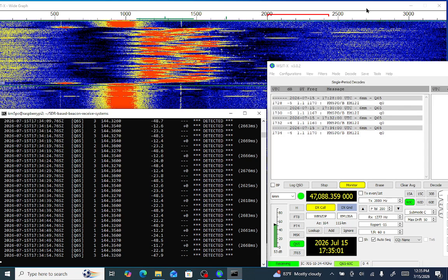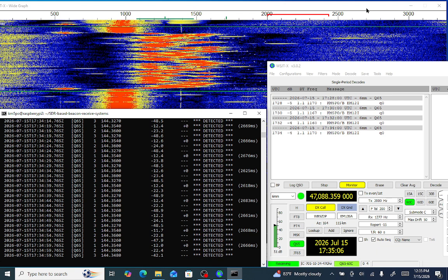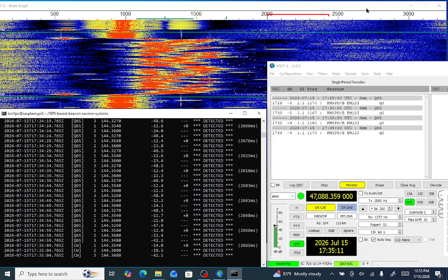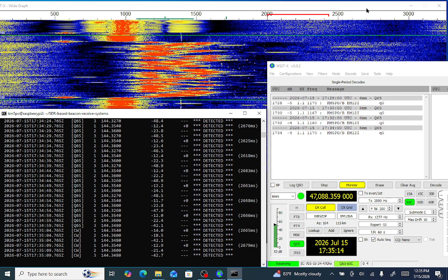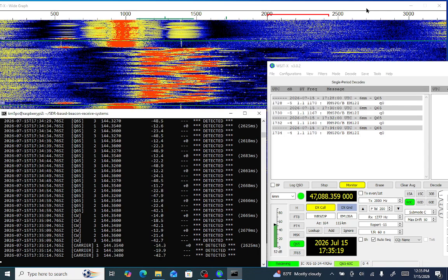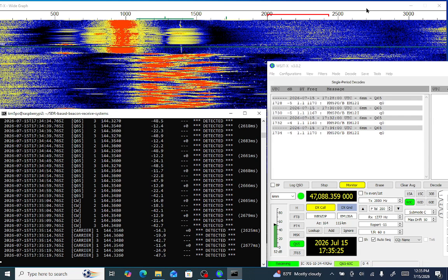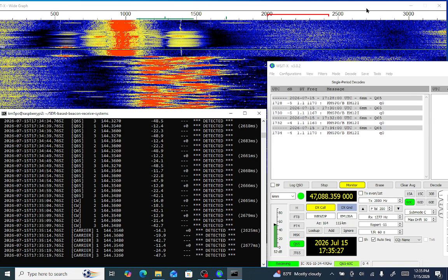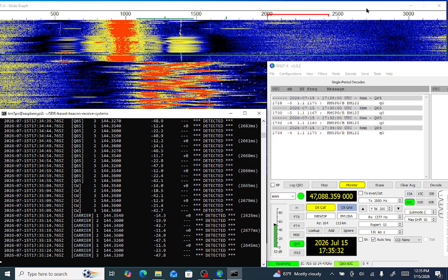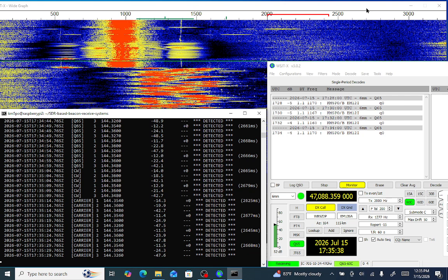So we just got a decode there at 1734. You can hear the CW ID, and momentarily you'll see CW down at the bottom in the monitor window, as it's indicating it's in that 10-second period where CW is, and it's just using the time to stamp in these modulation types. No magic there. So now I'm going to turn the VFO dial on the IF rig to 354 so we can observe the indoor beacon, which has a different call sign.